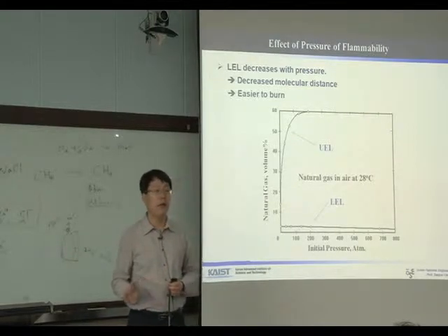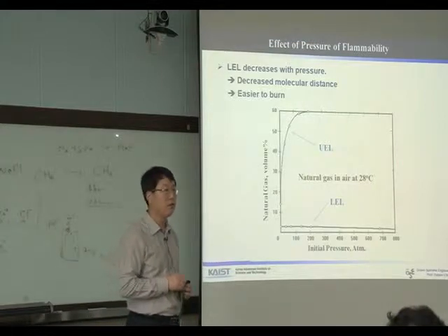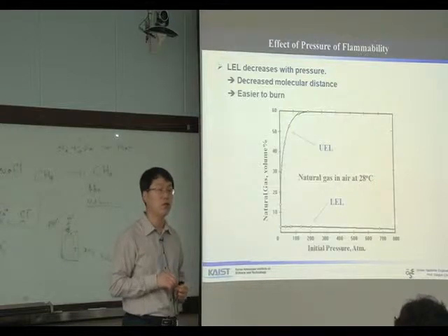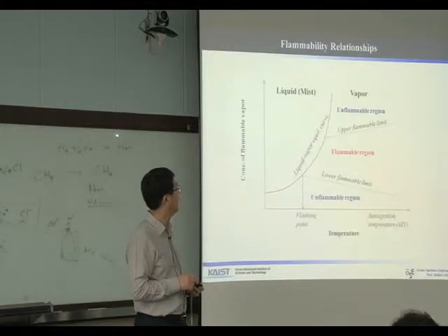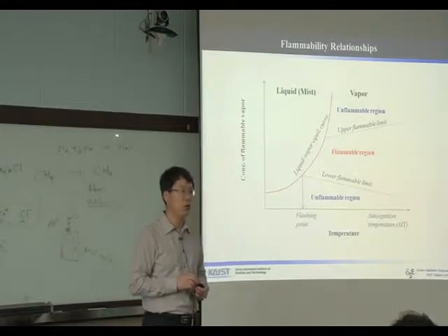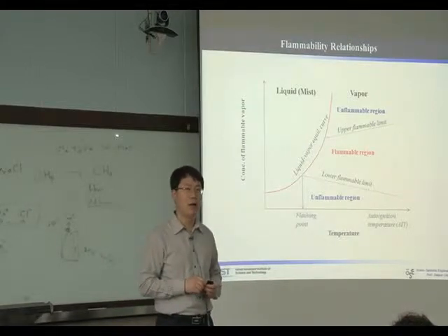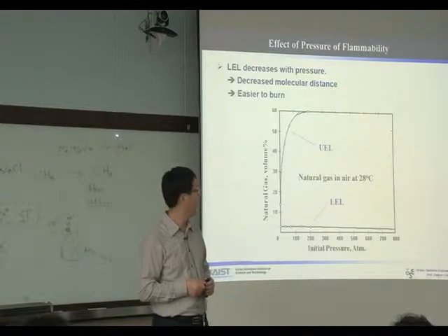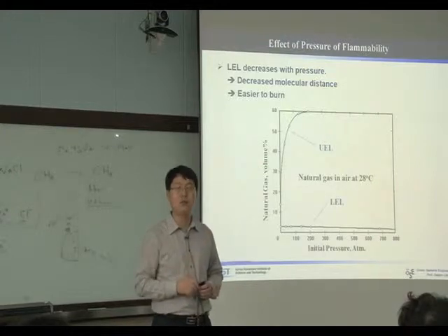In the same way, we can ignite the mixture more easily at higher pressure than at lower pressure. Do you agree with me? The previous diagram, the area is decreased with the pressure. Yeah, LEL is decreased with pressure.